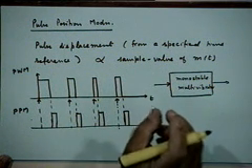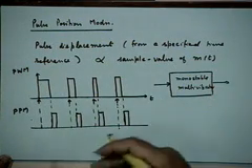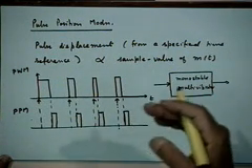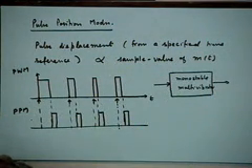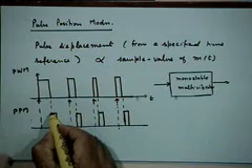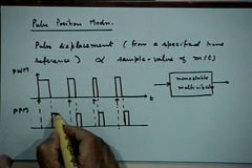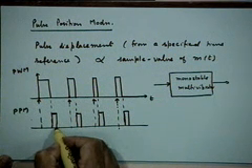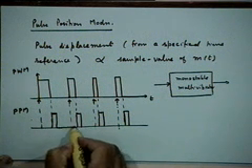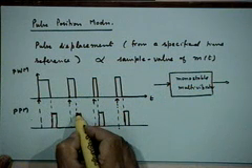It will stay in that state for some time and come back to the stable state. Let us say the unstable state corresponds to a 1 output, and the stable state corresponds to a 0 output. So it temporarily produces a 1 output. After some fixed time, it will come back, which is what you want. You want temporarily to go to this 1 output, and after some time come back to the stable state, which is a 0 output, and stay there till the next trigger comes.